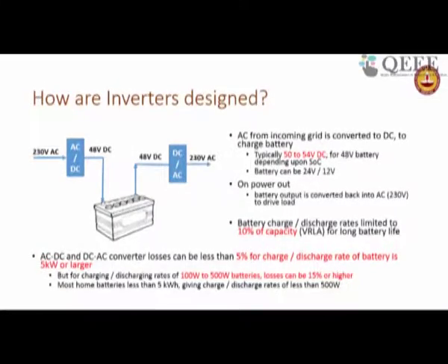Can you design a 100 watt AC to DC converter from 230 volt AC to 48 volt DC? Take it as a project. Excellent undergraduate project. Very simple thing, you will say. 100 watt only, so not very large power. Let's have losses less than 10%. Tough to design. You can design that. Remember that you can design that, but it will become very expensive.